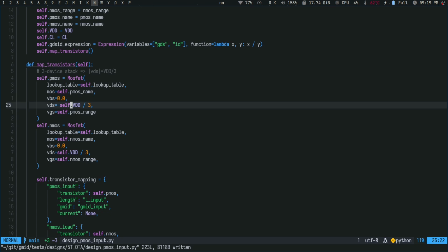When it comes to MOSFETs, we know that VGS is more important than VDS, because this is the voltage that specifies the current, whereas VDS can have an effect, but it's not that important. This is why I'm fixing VDS here. This is standard stuff. It sounds like I'm saying something important, but actually it's not.